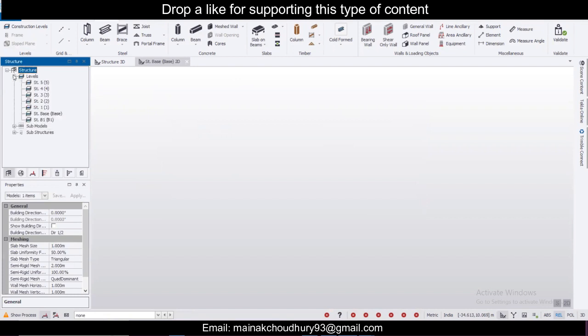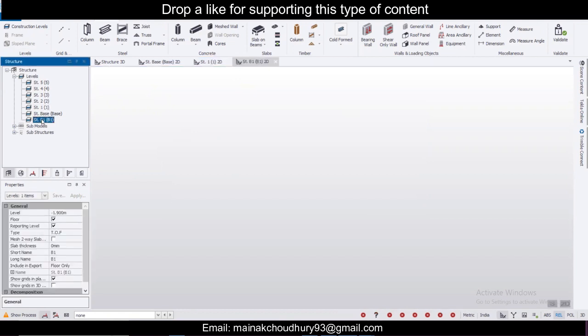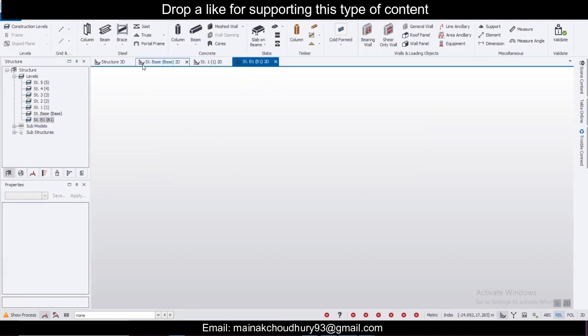And if you want to see whether the changes you've done are OK or not, go to the structure window and then open the levels, and you can see any one which you click. Double click and this will open. Suppose I want to open the foundation, double click on the foundation or B1, this will open. This is the structure 3D. So we'll go to the plinth level of the structure base and we'll work here. So we'll go and create the grids here.